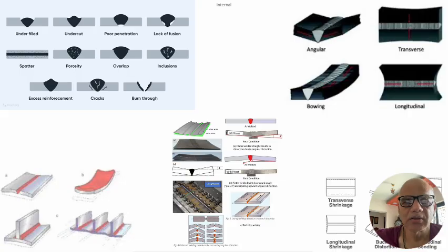That means the excessive current has melted material more in the last layer because you are in a hurry to finish and go. But it has not actually burnt the parent metal which is required. The parent metal has to also melt to have proper bond or a fusion. If that doesn't happen, overlap is not good. Otherwise, having 1.2 millimeter overlap on each side is a desired welding practice, and one should have it.